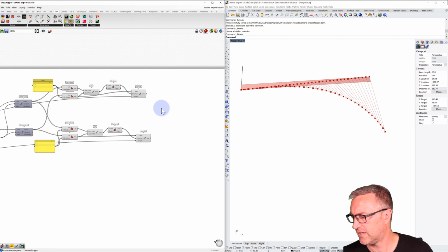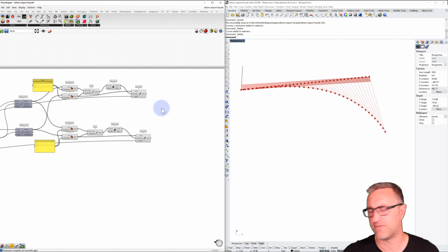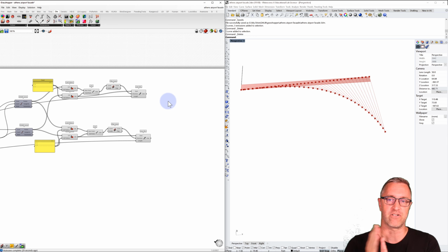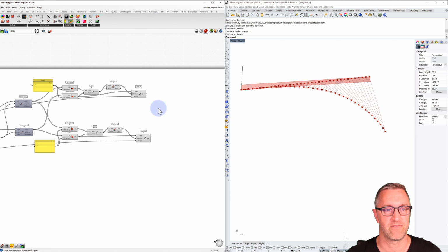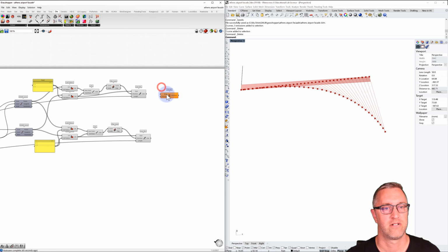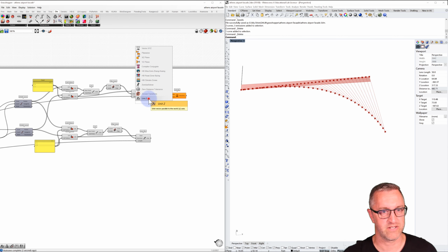I think that makes sense for us to add that height. So what I'd like to do is extrude both of them, and it's going to be the half increments along there, with an idea that we'll move one row up to occupy the second level. But let's start with an extrusion. The base will be our line. The direction will be Z.